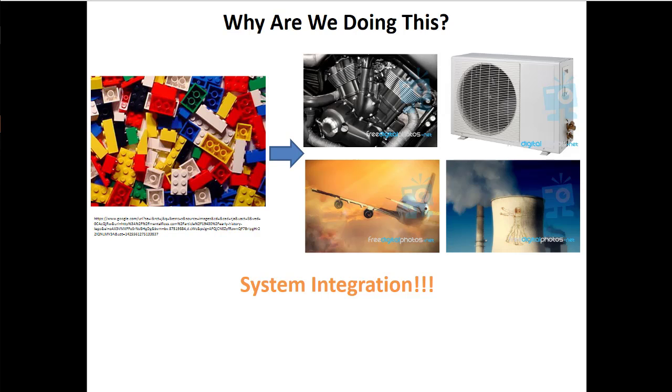They need to be two independent intensive properties. Three of the answers, one of them was always extensive, like maybe volume or mass. And two of the answers, one of them said temperature and pressure, which is true most of the time you can fix a state there, but not all the time, because under the vapor dome, temperature and pressure become dependent.